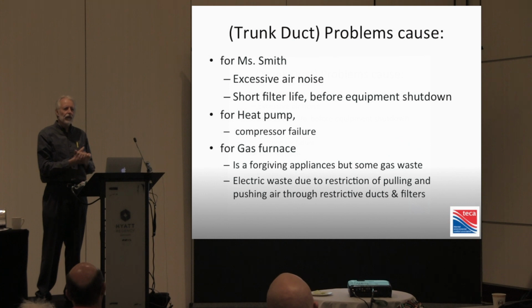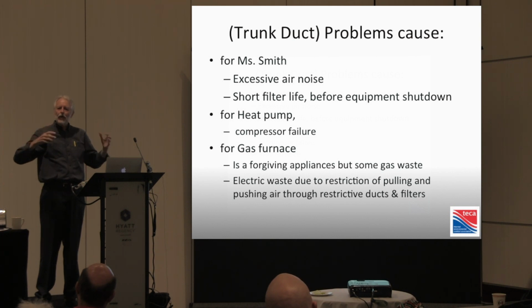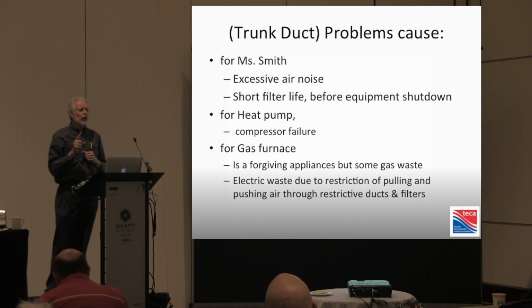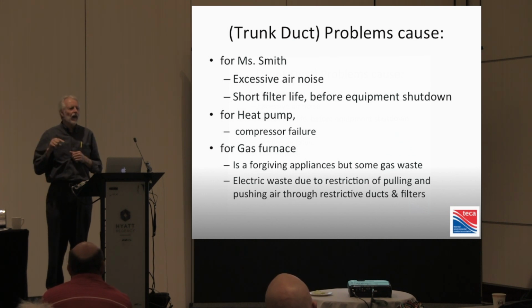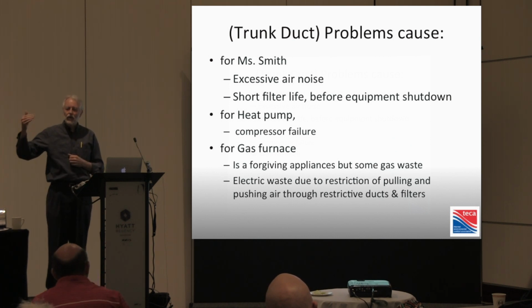And if you don't move enough, the equipment is not happy. That equipment has a certain degree of what we call static pressure capability, which overcomes the resistance of the duct that we have installed on that furnace. The problem is the furnace doesn't know the difference between the static pressure that's created by the ductwork and the grills and everything else, and on top of that, the filter is also additional static resistance.